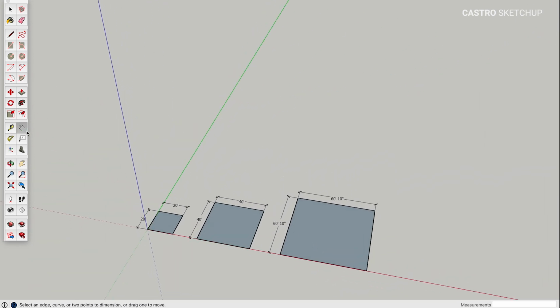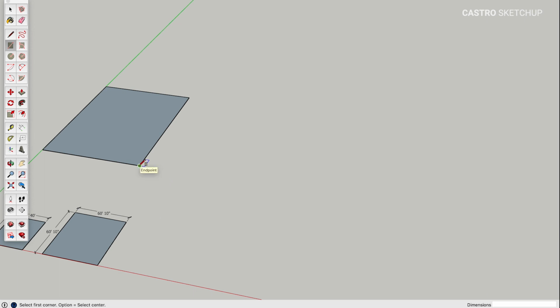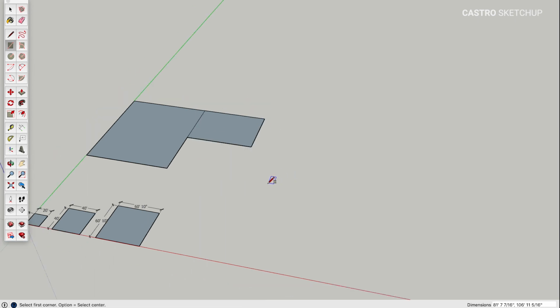Now, that was a sort of technical way of doing it, right? And earlier in the tutorial, I showed how to do it more freeform and manual. If you wanted to do it that way, you would simply click the origin point and then drag out however you wanted this to be, and then click. Right? So remember, SketchUp is a click and click program. So we're going to click, and then I'm going to click again wherever I want this to end, and there it is.